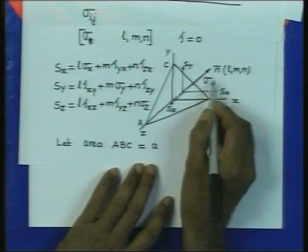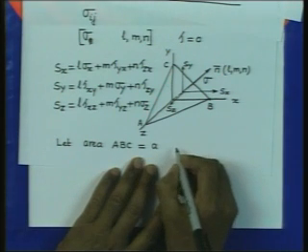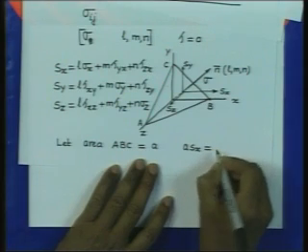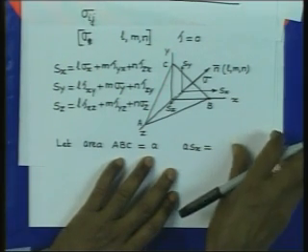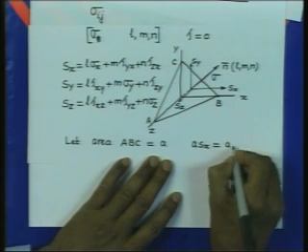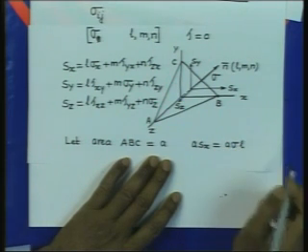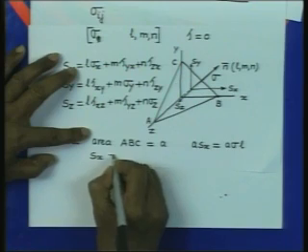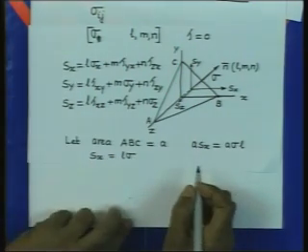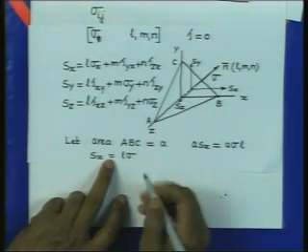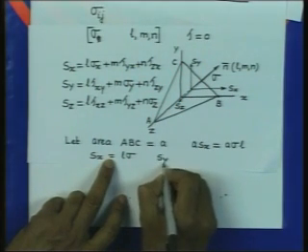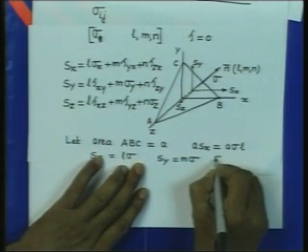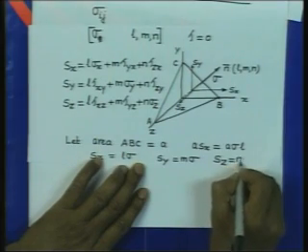Its component in the x direction is L sigma into A. So, therefore, we can write that the total force in the x direction is nothing but A Sx, and this should also be equal to L sigma A. So, finally, we get Sx is equal to L into sigma. Similarly, you can have consideration of force in the y direction, thereby you will find that Sy is nothing but M into sigma, and Sz is equal to N into sigma.